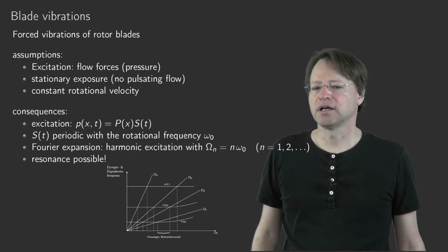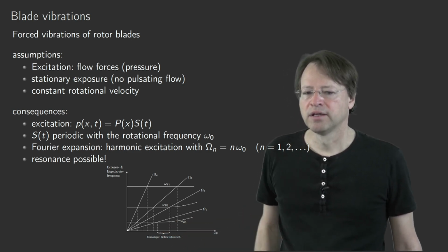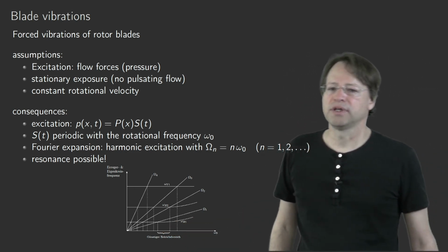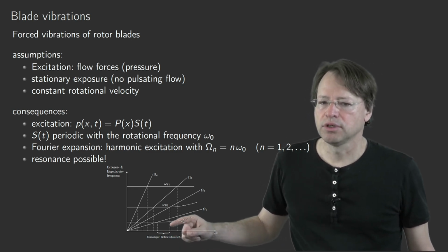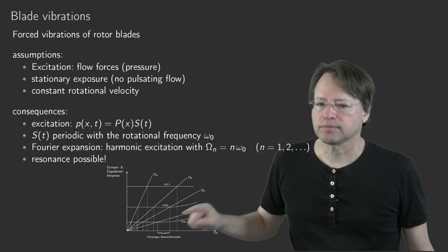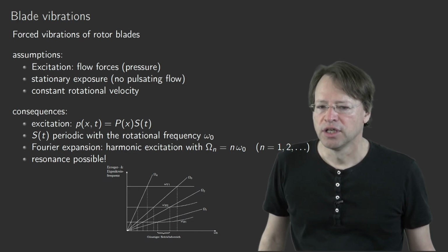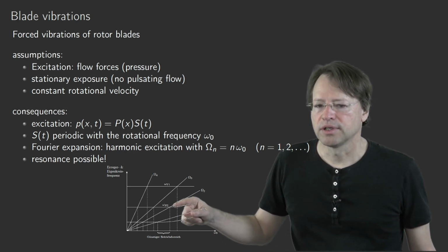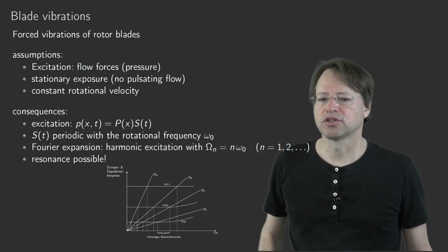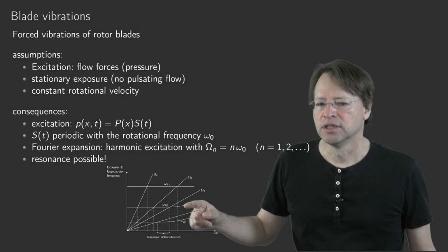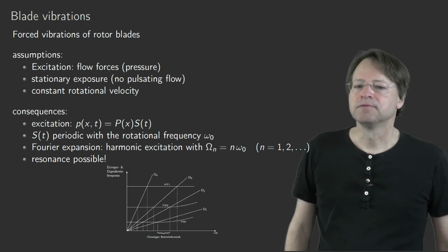What you should avoid are the first natural frequencies. And you can see here an interval for the operating speed of that rotor, which would be possible: beyond the resonance with respect to the first harmonic excitation and below the resonance of the bending natural frequency in the other direction with respect to the second excitation frequency.